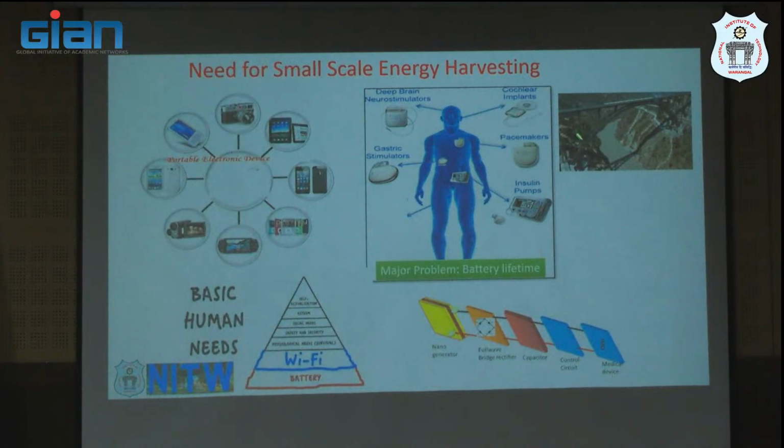Also consider bridges. Suppose you put a battery powered sensor here. Suppose the sensor stops sending signals, or maybe it is for railway track condition, whether the track is proper or not. Now the battery is gone, and someone has to go there and change the battery. It's too risky. You cannot go every time and change the battery. But if you can make use of the vibration energy from these tracks, if you make one device here which can power those sensors indefinitely, then you don't need to replace the batteries at all. This is what I am trying to do in my research work. So this is where small scale energy comes into the picture and makes an impact on our lives.